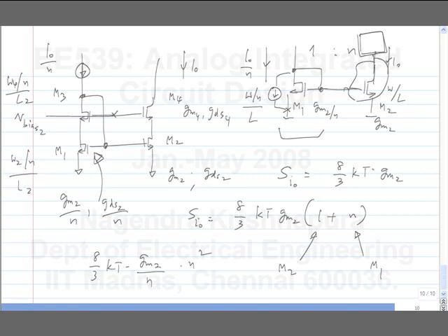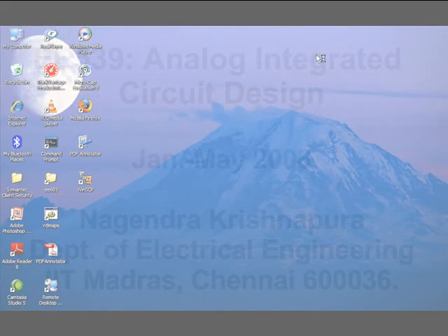A very large capacitor here will filter out the noise and reduce the noise spectral density, but the size of the capacitance can be very large. That again depends on the frequencies of interest. Even then, at DC this has no effect, so the low frequency spectral density will still get multiplied. Depending on the frequency of interest, you may be able to do this. The reason I brought this up was that's how we bias everything, including our differential pair.